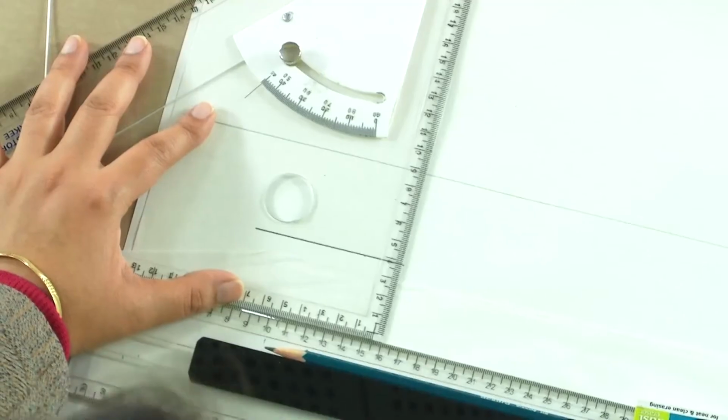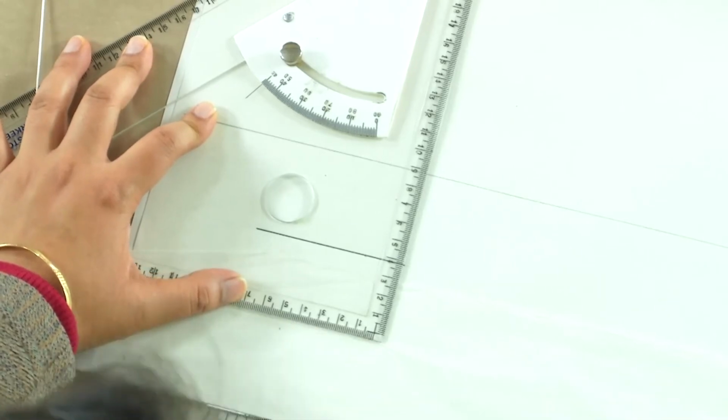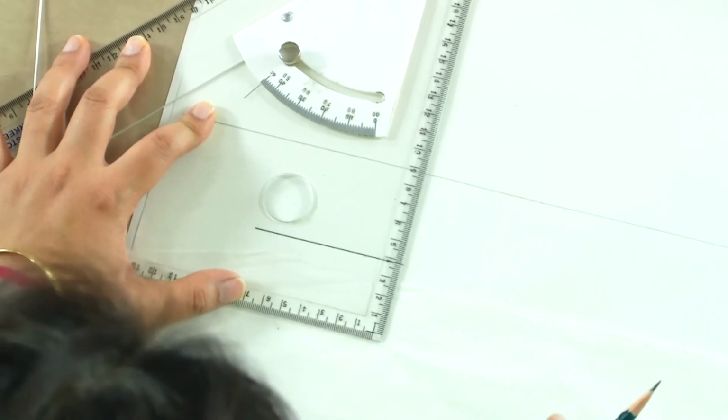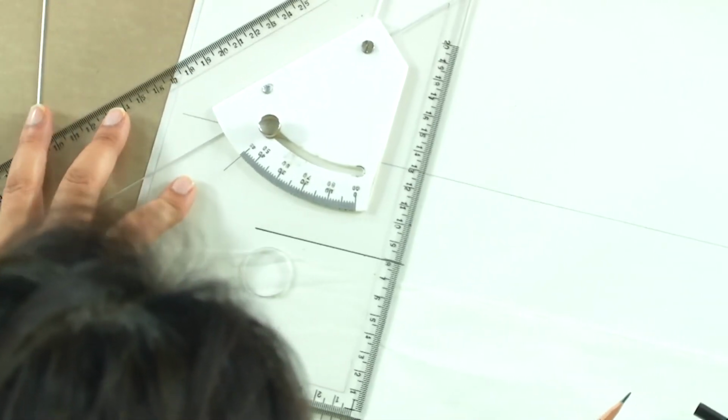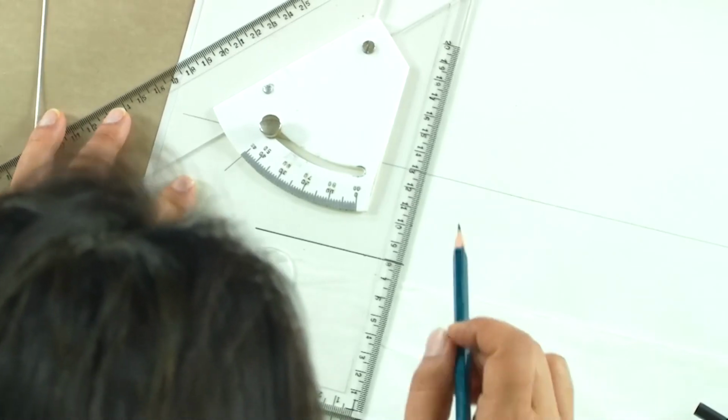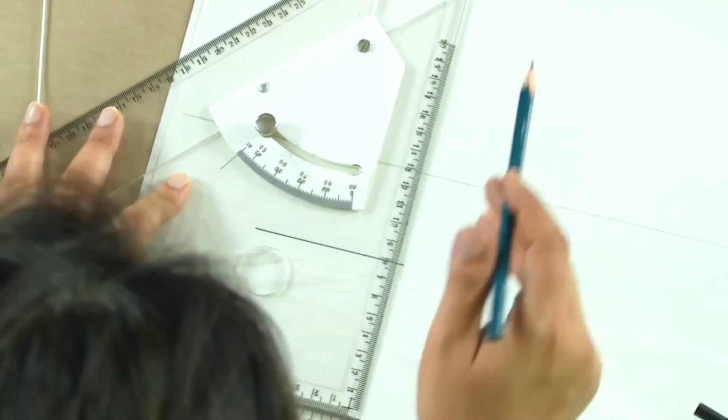Once we have drawn, we could start from the front elevation also, or plan also, simply because in our case the line is parallel to both the planes and we will be seeing the true length of the line in both the views. So, we could start from the elevation as well as the plan. I am starting from plan because it is easier at times to draw.